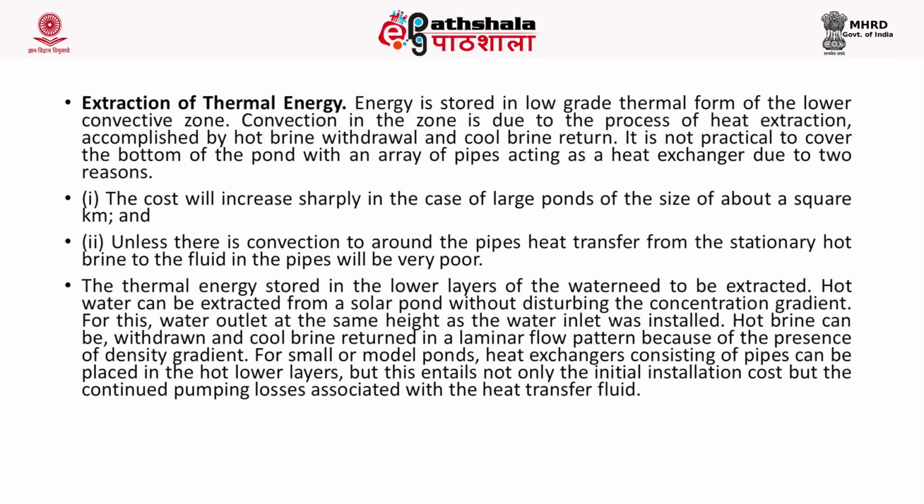For this, a water outlet at the same height as the water inlet was installed. Hot brine can be withdrawn and cool brine returned in a laminar flow pattern because of the presence of the density gradient. For small or model ponds, heat exchangers consisting of pipes can be placed in the hot lower layers. But this entails not only the initial installation cost, but the continued pumping losses associated with the heat transfer fluid.